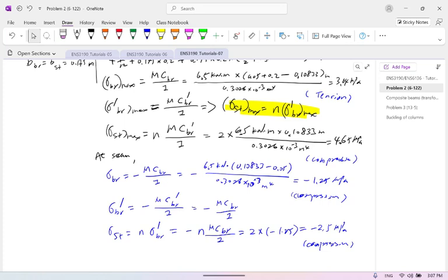The only new thing is the n. How can we work out the n? n is equal to the Young's modulus of the material to be transformed over the Young's modulus after transformation. Okay, that's the way we can work it out. So remember, please practice. This is very important for you because this is from real questions of the last few years. That's why I always mention where this is from, letting you know. So please keep practicing, understand how we can work out these questions.